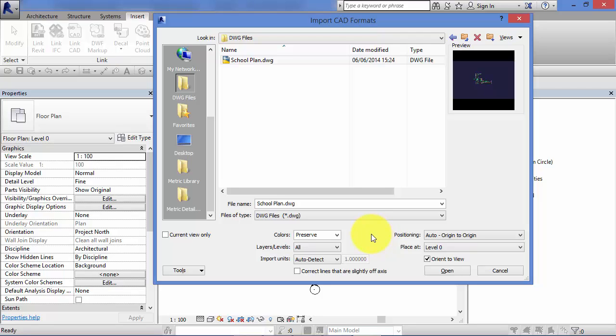Personally, I want that DWG to come into Revit exactly as it was surveyed. Then I can decide the status of those lines. We can approximate them when we put walls over the top, but if you have that ticked on, you have no way of knowing which lines Revit has manipulated, which ones it's adjusted. So I would always turn that off.